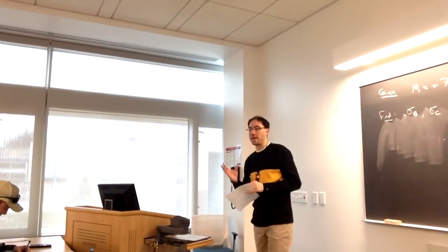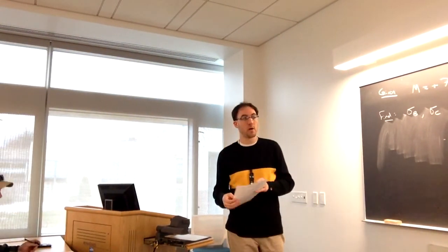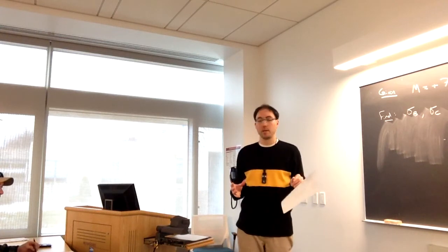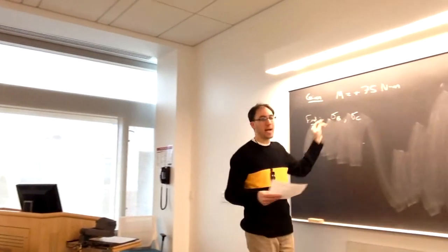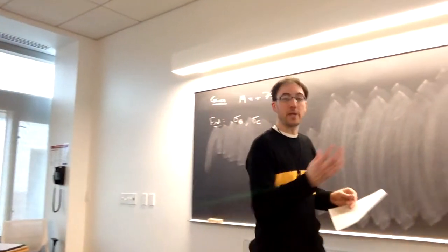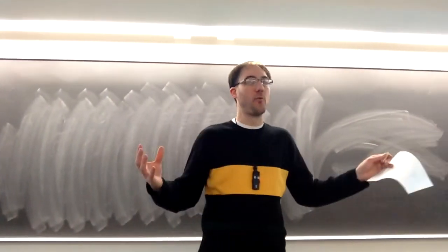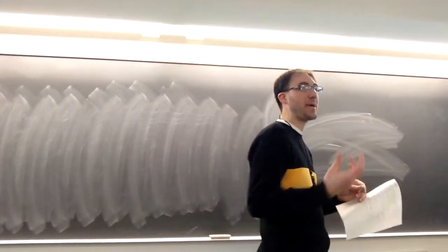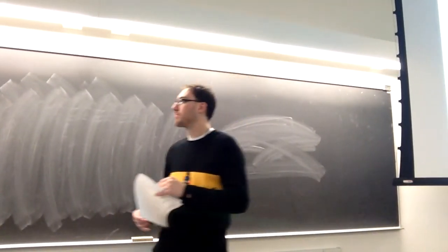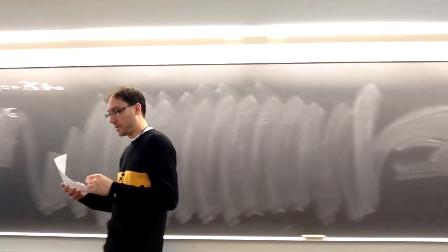And note in the picture there is no internal normal force here, which is also a normal stress. And what we'll find when we do combined loading towards the end of the semester is we could have bending and an internal normal force, both of which are going to induce a normal stress that will be additive. Right? But here we just have the bending moment.